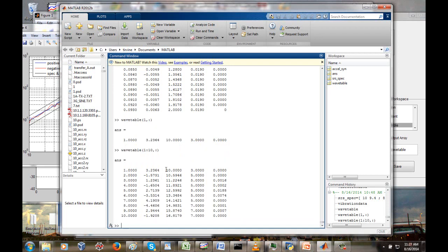Okay, in this case we don't have that funny 1,000 factor anymore. This first column here is really meant to be an integer, and that's the wavelet number. Again, we have acceleration in g for the wavelet. Then we also have the frequency in hertz for the wavelet. We have 1/12 octave spacing, which means as we double the natural frequency, there's 12 steps.